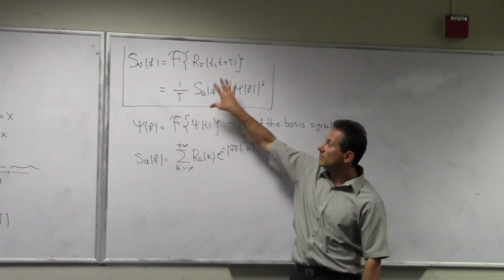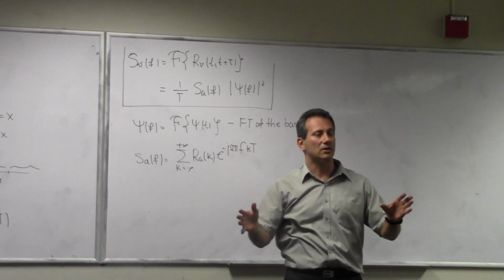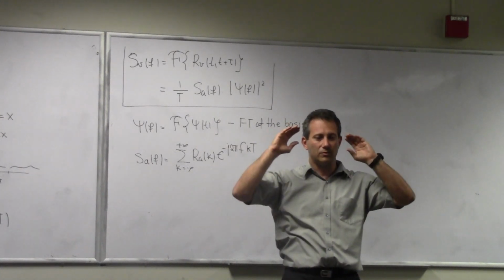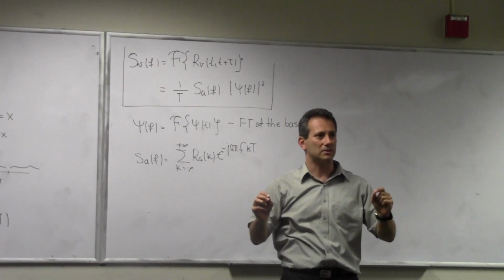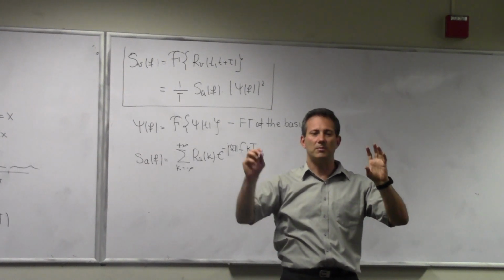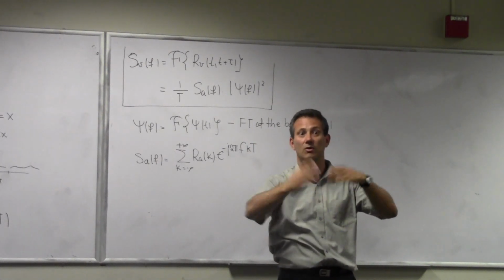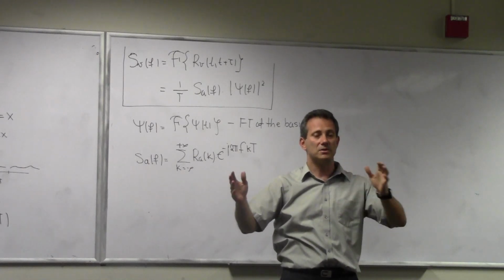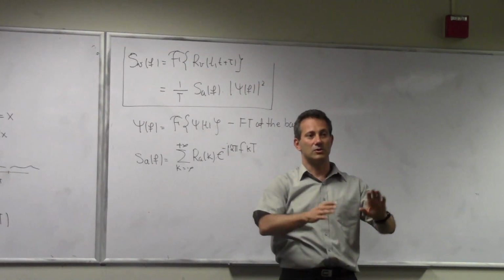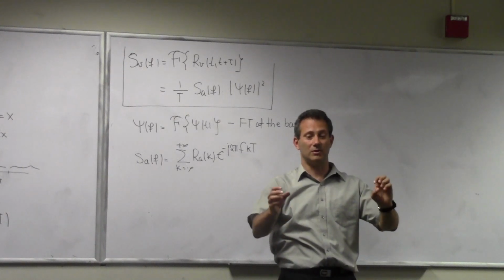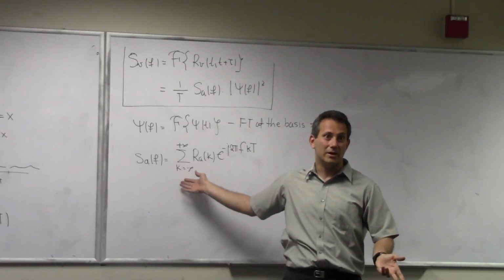I know it's a little bit elaborate, but this result is worth remembering. It tells you what the digitally modulated signal looks like in the frequency domain. If you forget everything else, remember that under most common circumstances, meaning you do statistical encoding, or maybe you convolve your bit sequence with a random PN sequence at transmission to make all the bits decorrelated, the spectrum of your signal looks like the pulse that you have selected for the signal, which is a remarkable result. On the outset, you don't necessarily see why it has to be that way, but it turns out it is.